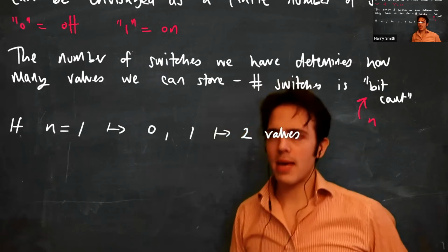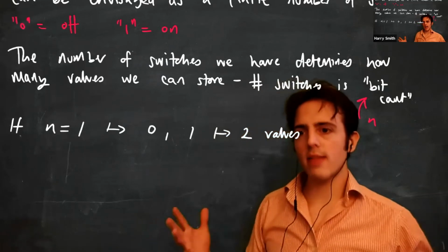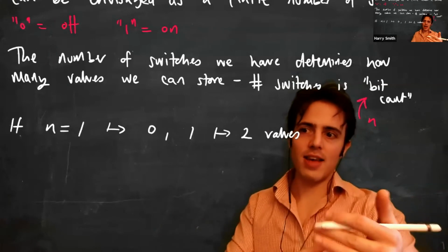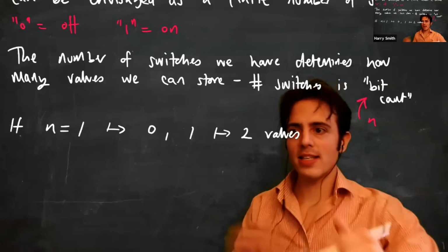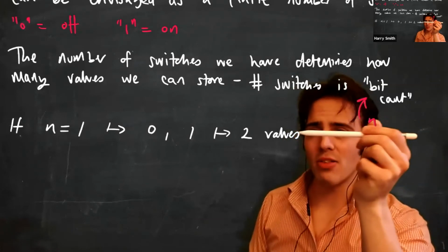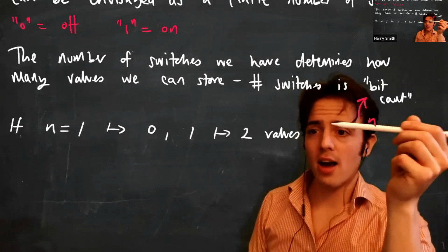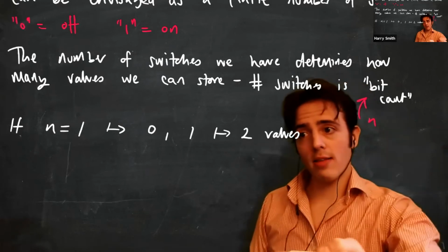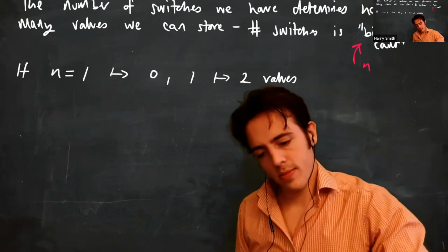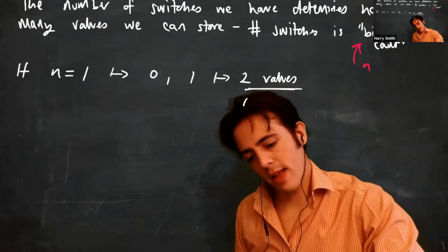So what does that mean? That means that if I've got a 1-bit ADC that's capable of taking anywhere from -10 to 10 volts, it can only separate them down into 2 bins. And it's going to say something is either anywhere from 0 to -10 or 0 to +10. Let's just write that down. What does this mean?